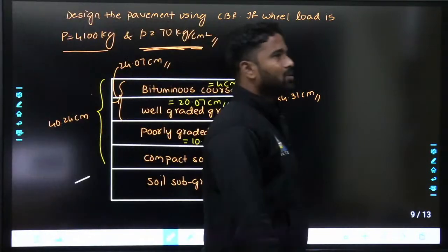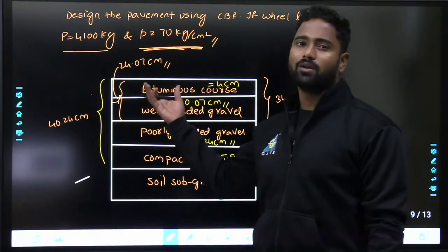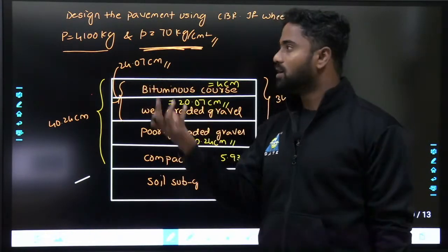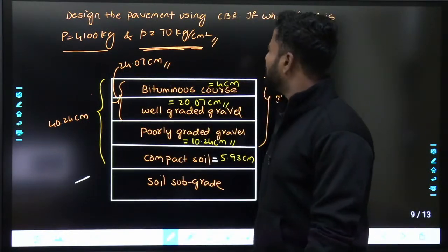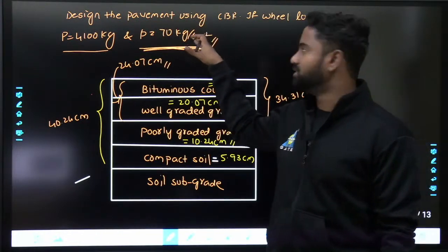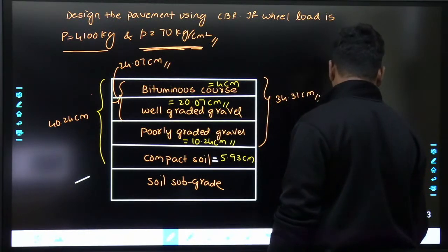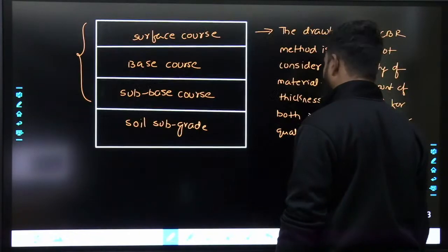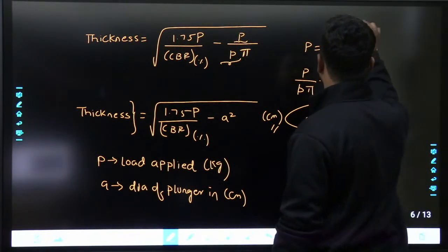See, this load is the load that is given to you. It's not average wheel load, it is total wheel load. It's like two wheel loads, 2050, 2050, 4100 kgs, and generally P will not be this high. This is pressure, contact pressure or tire pressure. P is indirectly stress, generally in the range of 7 kgs per centimeter square. Here, the small p that I have given is contact pressure